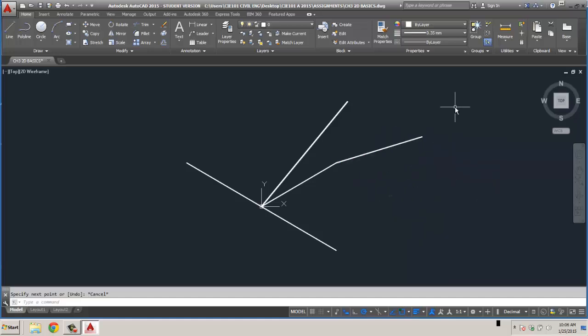It looked like it was going the wrong way. Let's try it again with another one. If I just come off this point, we'll go over 5, hit comma, and we'll go up. Even though it looks like it's going off, let's key in 1. So it's over 5, up 1 from this point. So that's a relative coordinate point. Okay?